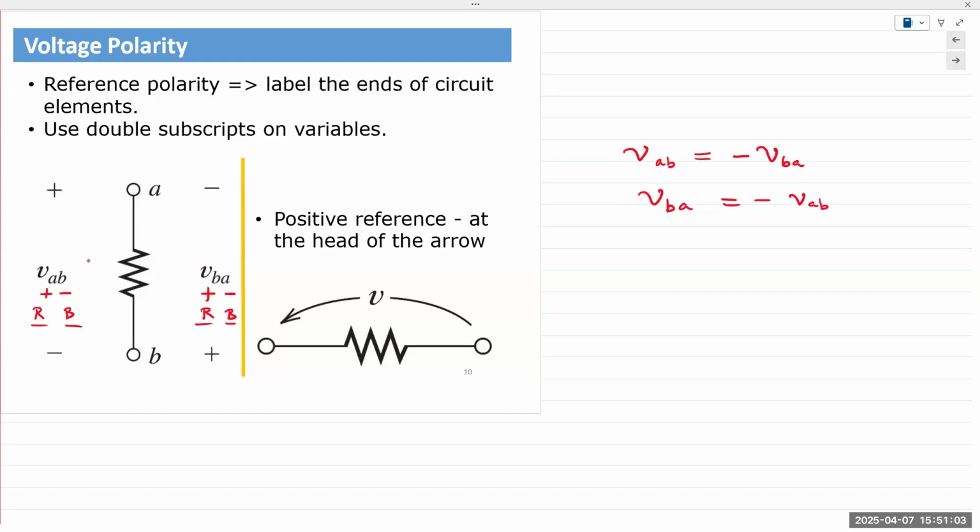But electrically speaking, if you're modeling a charger as part of an electric circuit, that's a source, so it'll have a minus sign in front of it, right? So in real life, you'll just say it's a 10-watt charger. It's not a minus 10 watt. But if you write a mathematical expression for that charger, it'll be minus 10. In the same way, voltages and currents are never negative. They are simply negative from the perspective of the reference point. Is that clear to everyone?